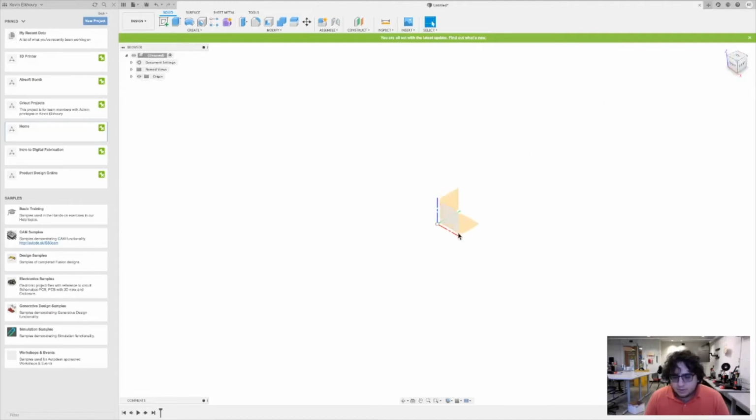And there we go. Now that we have this set up and established, we're going to actually make our first design in Fusion 360. So, what's different about Fusion 360 and the idea of sculpting is that when we're working in Fusion 360, we actually want to be thinking about our designs in a 2D sense. We want to take a complex 3D design, break it down into multiple 2D components that can be simply pulled up, or as the word that we're going to be using in Fusion 360 is extruded, in order to make a complex 3D design. And we're going to do it right here.